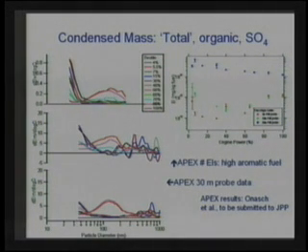We're looking at particle size distributions on the left panels. Here, just looking at the total with an SMPS, starting at low powers, that's the black curve, we see it's dominated by the volatile contribution. And the larger particles, which shift in size somewhat going from low power to high power, shift over to here as the soot mode grows in, with a concomitant decrease in the number of volatile particles. And so we're seeing that in the total number of particles.